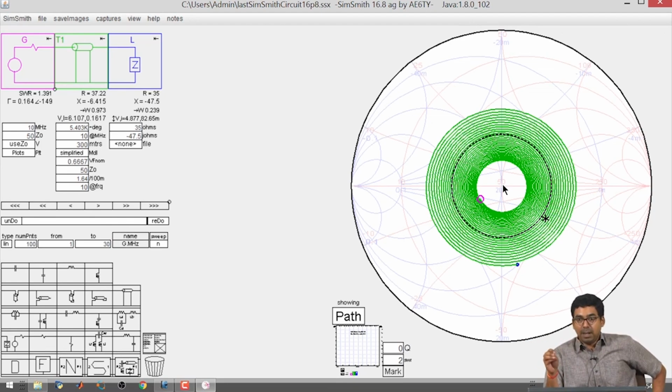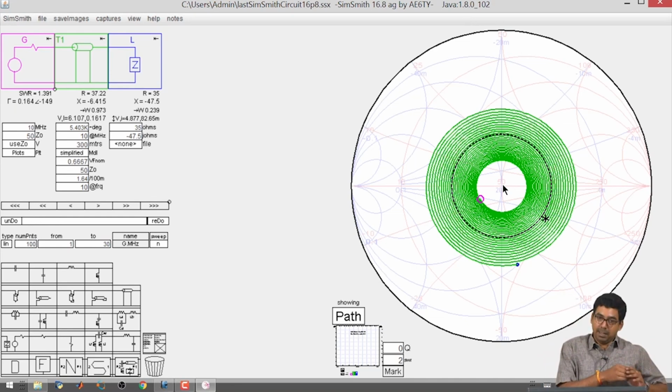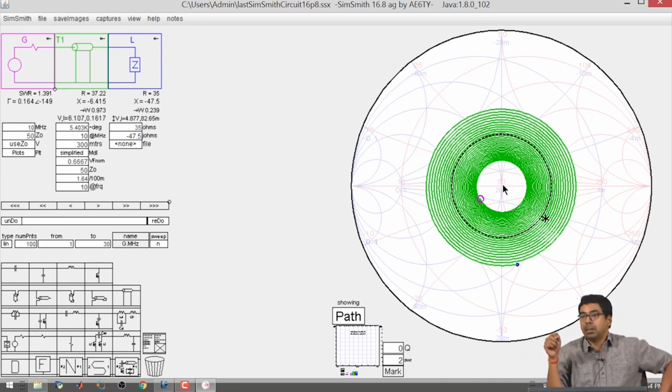Okay, so one has to be very careful about using lossless transmission lines. Otherwise many things can happen. The sender will believe that they are sending the signal, since they are not getting any reflection, it's going to the receiver, but the receiver will have the belief that there has been no signal sent, simply because your transmission line is eating all the power.